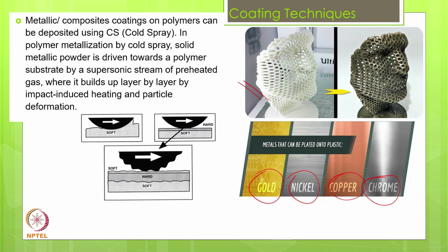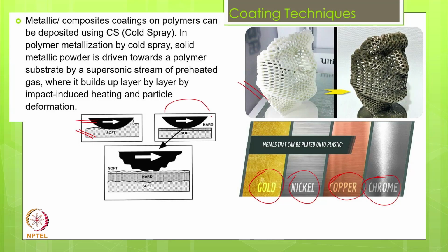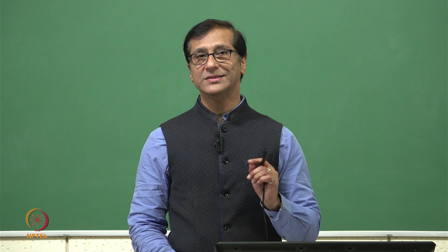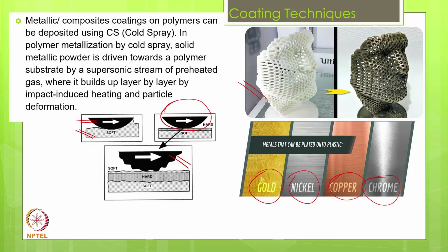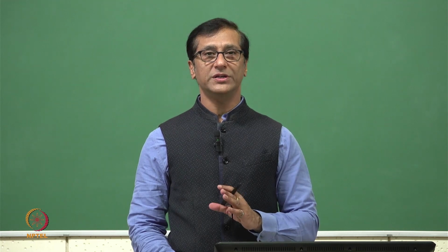The only thing that comes here is that the polymer is a soft surface and we are doing a ceramic coating or a metallic coating. One is that the soft surface should sustain the temperature, and second, the load should not go beyond the limit. The reason being that this coating can be only a few microns, it can sustain some load, but if the load increases significantly, then the soft surface will change shape. If the soft surface changes shape, then this hard coating may break. So there is a need to really make a coating with appropriate load and speed conditions.